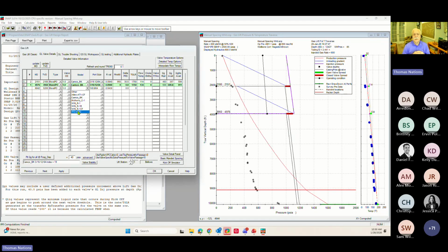So now that I'm looking at this, I can tell you about Valve Performance Clearinghouse. It's actually run by the LSU petroleum engineering department. We started this about 20 years plus ago as an industry consortium. We wanted to investigate how gas lift valves actually performed. What is the throughput through a gas lift valve given a certain set pressure on the gas lift valve and upstream downstream pressure relationship in a dynamic flow loop? How much flow rate can I get through that valve?